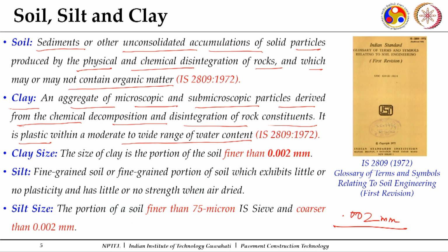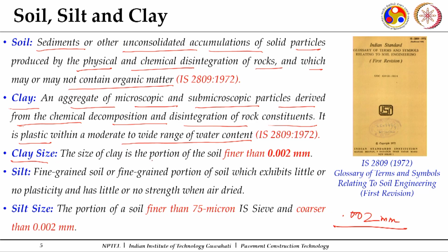Now all these aspects will be related to pavement engineering, especially transportation engineering. Normally the people working in soil engineering go into very in-depth study of these soil characteristics, but here we will focus more on those which are quite relevant to our pavement construction or road construction aspects. So they say that the clay size is normally one which is finer than 2 micron.